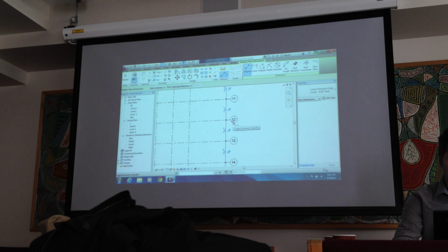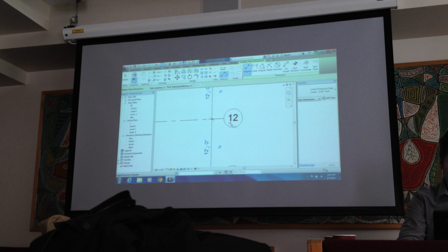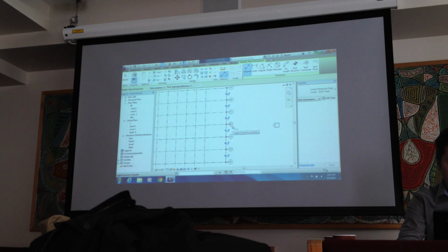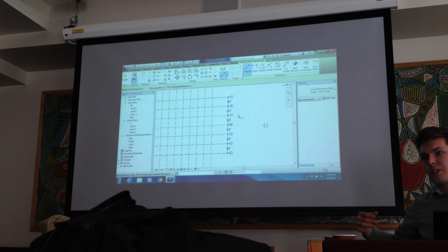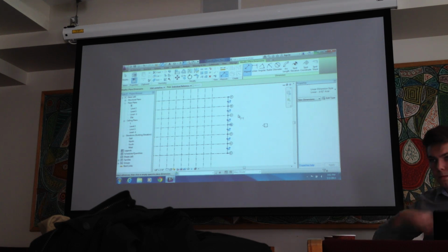But the main thing that you would want to use for this part is if you want yours to all align to an exact unit. You can see it's kind of hidden right here, but there's a button called Toggle Dimension Equality. So you can click that, and it will align all of the dimensions that you have, and it will change the grids to align to your system so they're all at an equal distance apart.